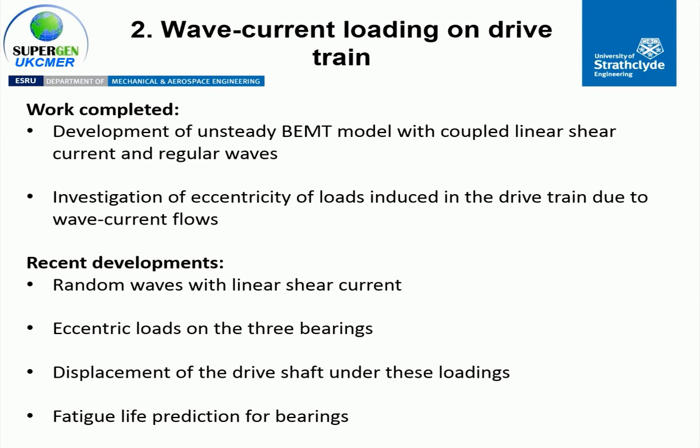So Thomas Nevalainen has been developing an unsteady blade element momentum theory model, which includes linear shear current coupled with regular waves. And he's been using this model to investigate how the variation in the loads across the rotor plane, and then how those then transfer to eccentric loads on the drive shaft. The most recent developments in this work are firstly adding random waves into the modelling, and then looking in more detail at how the loads are transferred to individual parts of the drivetrain, so specifically looking at the loads on the individual bearings.